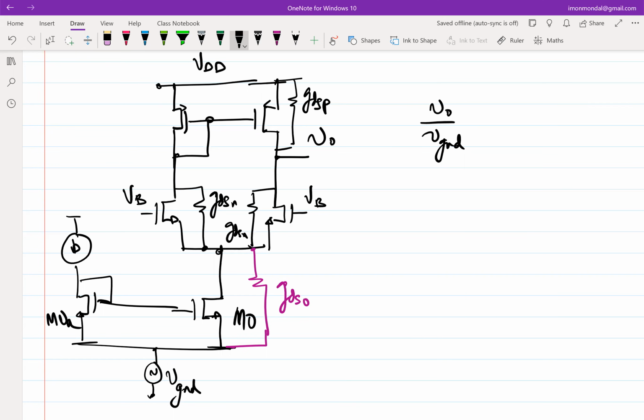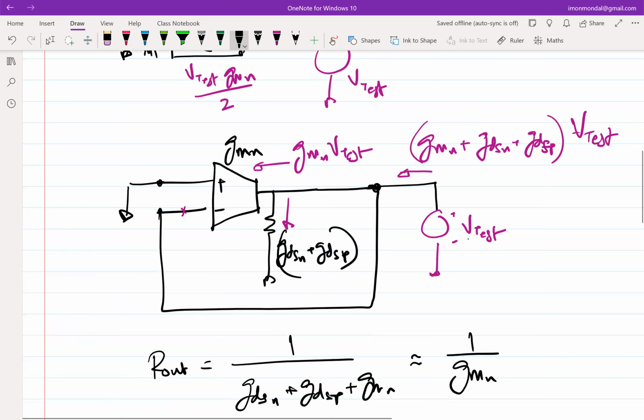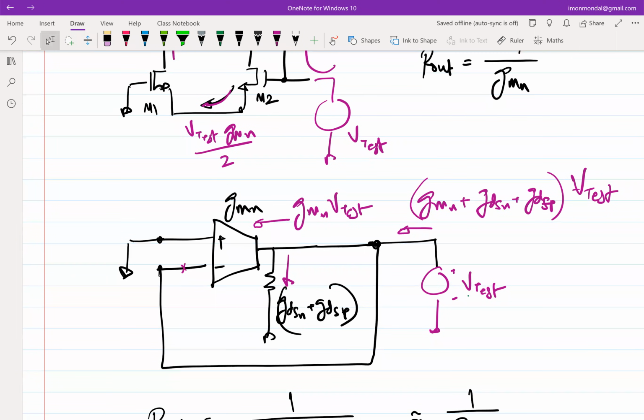Correct, exactly. So yeah, that makes sense, because her question is that in the previous case, your R out is changing, which means gain is also changing, right? Obviously, gain is changing, because this is under what configuration? This is essentially a unity gain feedback, kind of a buffer, right? And the whole purpose of what we are doing is essentially to make a good buffer, because it's supposed to be driving any load.